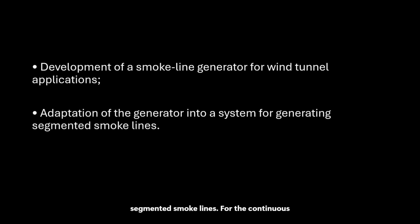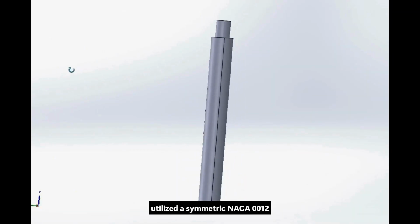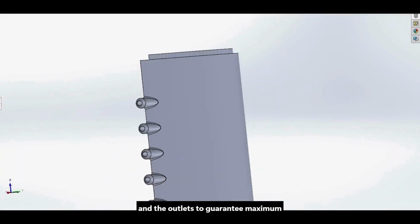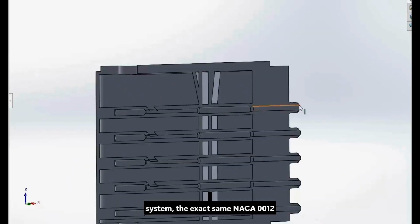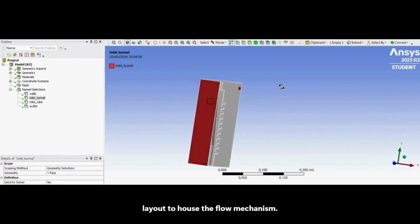For the continuous smoke line generator, the geometry utilized a symmetric NACA 0012 profile. The inner volume was reduced by a factor of 0.25, leaving minimal space between the manifold wall and the outlets, to guarantee maximum mass flow uniformity. For the segmented system, the exact same NACA 0012 aerodynamic profile was maintained as the baseline design, adapting the structural layout to house the flow mechanism.